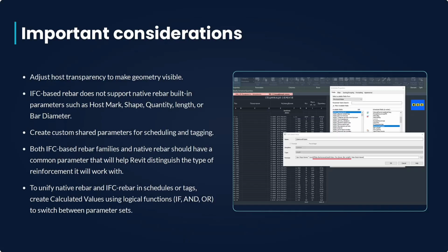Important considerations: you must adjust host transparency to make the geometry of the family visible. IFC-based rebar does not support native rebar built-in parameters. Therefore, you must create custom shared parameters for scheduling and tagging.